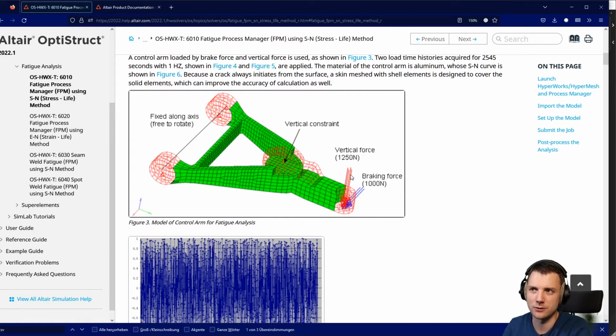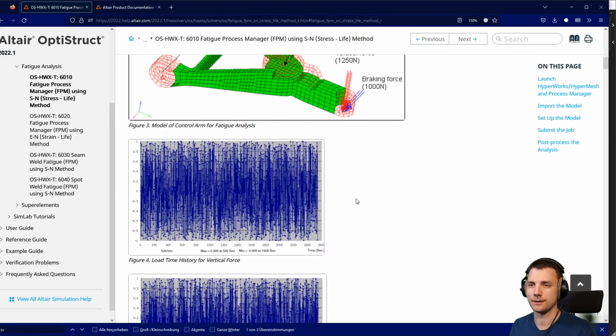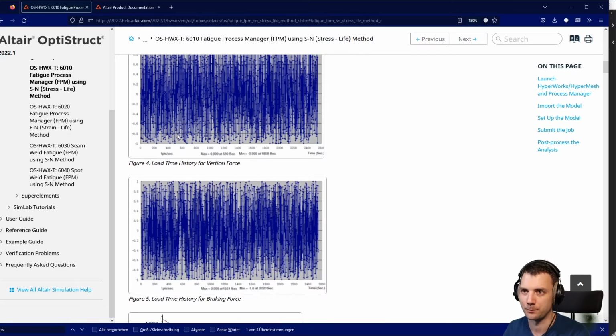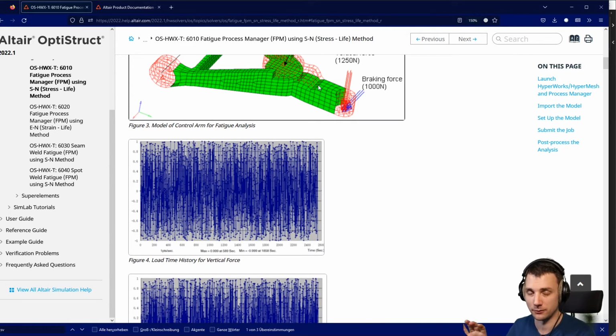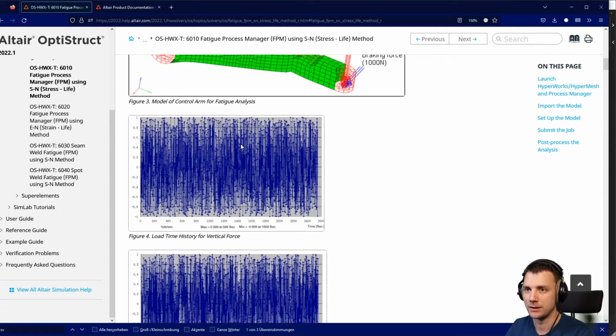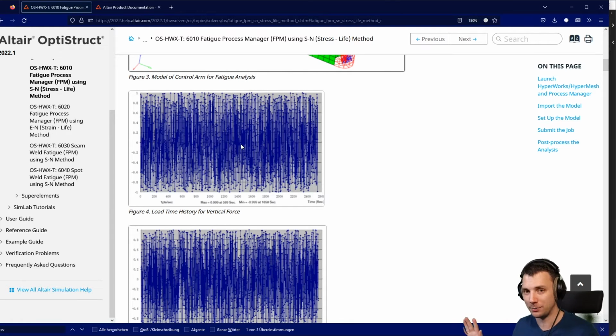So you get a relationship between force and stress for each element in static load cases. And then you sum up your damages over the time histories by scaling the stress values gotten from the static load cases onto the time history series and then accumulating. And accumulating is also a whole topic for itself, because you would not just go from every point to the next point and get the delta and then just do something with that.